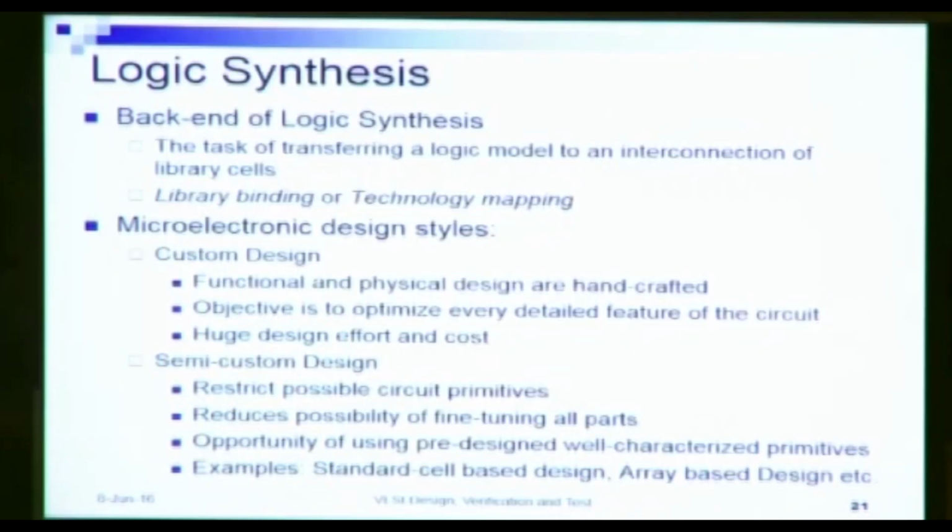Also, there can be different design styles here. You can have custom design and semi-custom design, for example. In a custom design, the functional and physical design are all handcrafted. So everything is done by hand, and hence the objective is to optimize every detailed feature of the circuit. Obviously, if the circuit is very complex, if it is huge, then such a design is impractical to be done in practice, because it will incur huge design effort and cost.